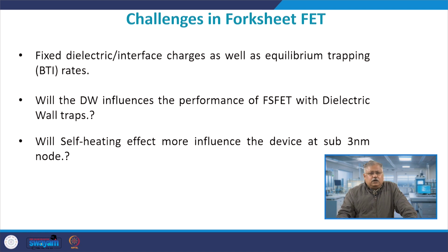And therefore, when you consider the BTI effects, the effective rate of trapping and detrapping of the charges will depend upon the position of the traps with respect to the interface. If it is well within the oxide layer, it will be very difficult for it to trap charges in the channel. Whereas if it is very much inside the channel, it will be relatively easier for it to actually accept the charge carriers, right? It's relatively easy to handle.